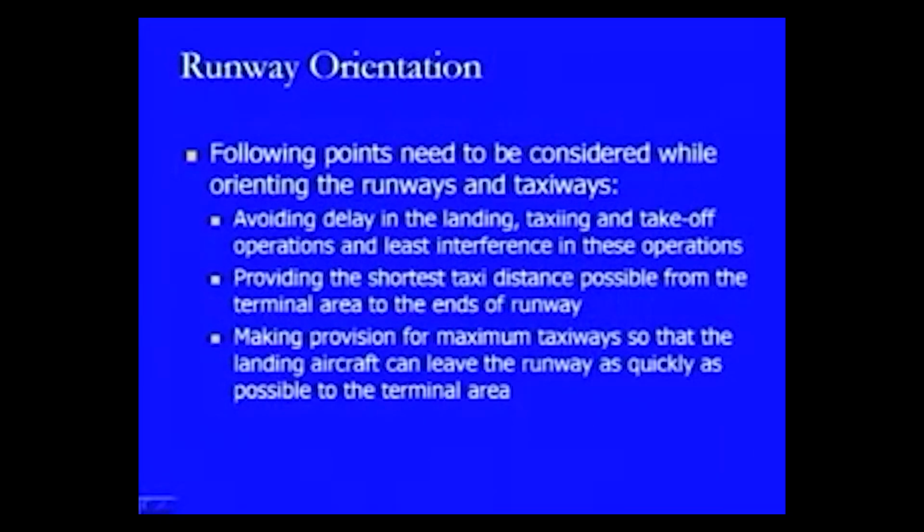Then making provision for maximum taxiways so that the landing aircraft can leave the runway as quickly as possible to the terminal area. Now, this is important in the light of the different types of aircraft which are going to use any landing strip. Not all the aircraft are of the same specification. If the aircraft are of bigger size with a big amount of power available to them, then they will be moving a larger distance on the runway strip before they start taxiing. Whereas, if the aircraft is of a smaller size, then it will start taxiing at a much earlier time frame.